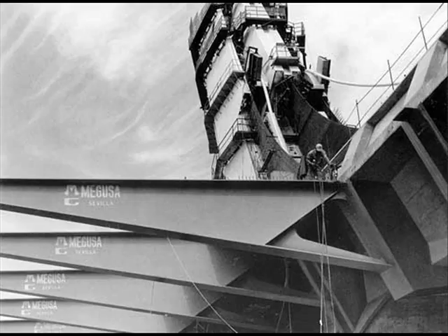In terms of materials, we can see in this picture that the mast or pylon was made of hexagonal steel plates reinforced with concrete inside. The deck is designed with a metal structure and consists of a central triangle and hexagonal shaped anchors where the axis of the straps are.